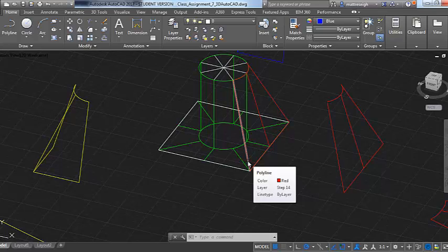The advantage of doing this part like this with heavy duty ducting is that all I'm having to form in the press brake is down to this single point. I would just have to press brake this round on top, and then I can stack them all together and weld up this seam. I prefer this method for ease of handling on a press brake and only having to worry about forming one end one way. I don't have to worry about making a 90-degree bend down here along with forming something round here.